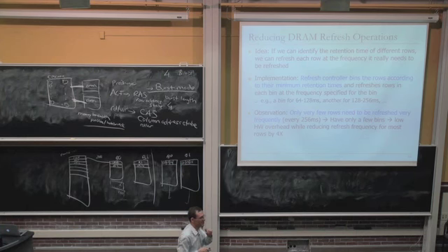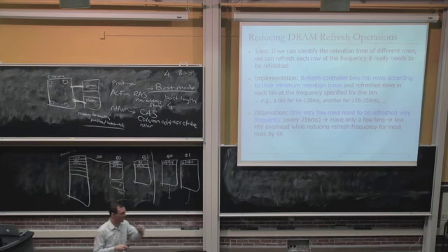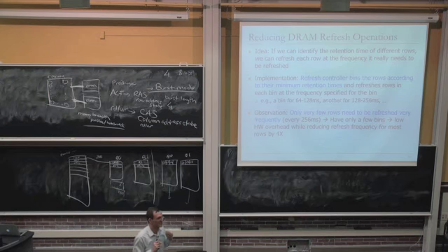So that's an excellent question, and those are some research questions that Jamie is looking into. You could create them dynamically when the machine boots up. Of course, then you need a very efficient way of creating those bins, right? But actually, the properties do not change across many different runs. So the DRAM manufacturer can store these things in the DIMM, and somehow there needs to be a protocol such that the memory controller gets these bins.